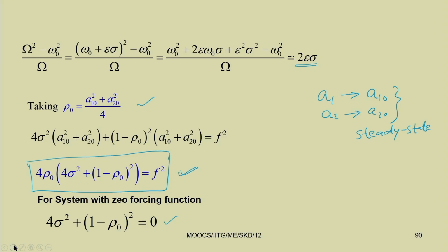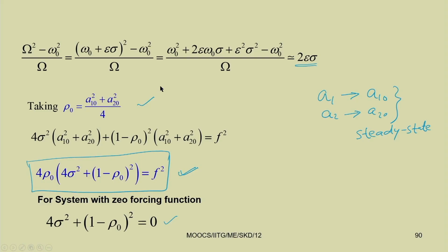Then, differentiating those things we have written down the equation, and using the trigonometric functions like sine cube and cos cube in the form of sin omega t, cos omega t, or sin 3 omega t, cos 3 omega t, or in the form of harmonic functions, then by taking the coefficients we conveniently get the equations, reducing to closed form solution.